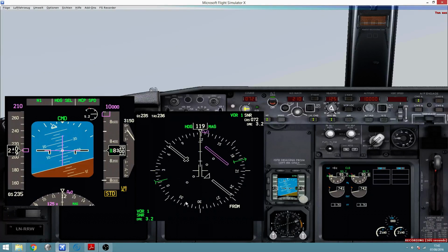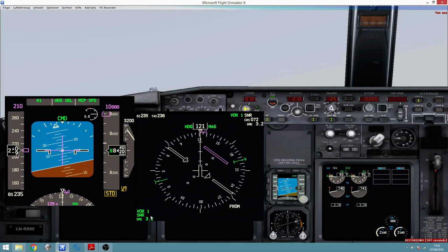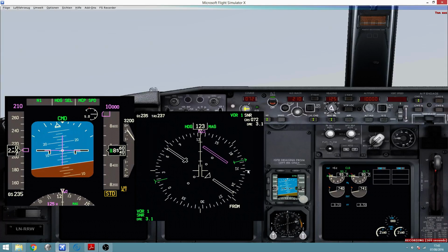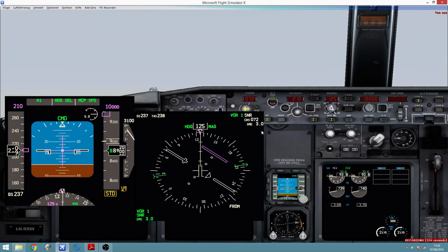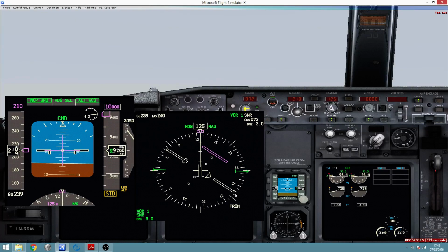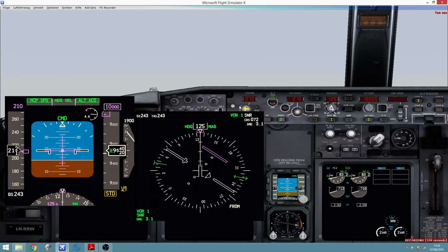All right? Good. Since we are really close to the VOR, just 3 miles, everything is very sensitive. All instrumentation. I'm crossing many radials in a very short period of time. So I will have to anticipate. Be aware that when this indicates that the VOR is here, that will mean that I am on the radial. When the VOR is at position 252 degrees of where I am, that means that I am on radial 072.